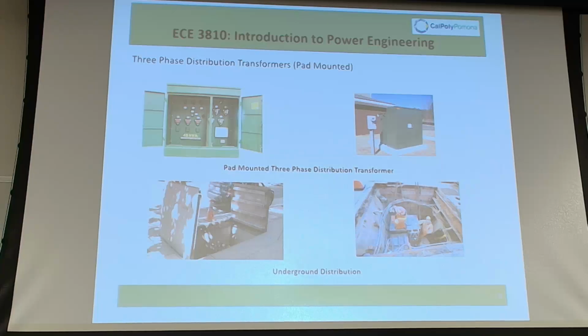As an example, the city of Irvine is the one that comes to mind. If you go to Irvine, you see some transmission lines, but you never see distribution feeders. New York's always underground. The city of New York is heavily undergrounded. And they have a lot of problems in New York, because it's a pretty old network.